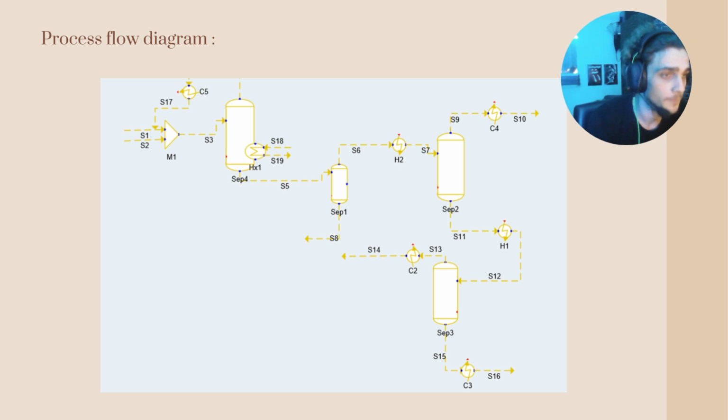the separator 1. The bottom stream of separator 1 is the catalyst, and the rest escapes by the top of the separator and is in excess. And it's basically all the products and byproducts of the reaction, so acetic acid, formic acid, and ethyl acetate.